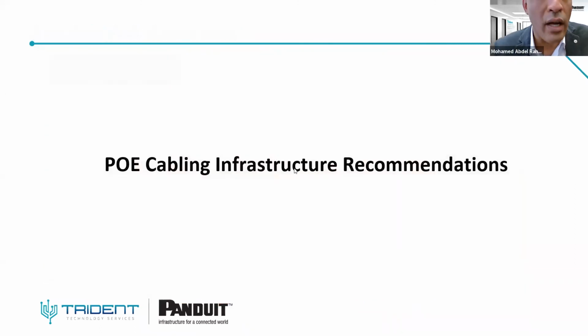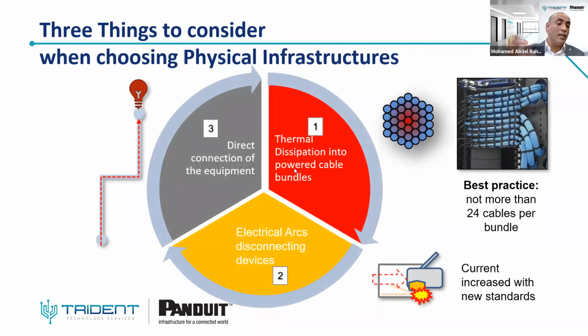So finally, you have only 2 minutes now, talking about the recommendations. What are the recommendations for the increasing high power? You need additional precautions when you are talking about cabling installations, to avoid overheating. You have 3 considerations when you are going to PoE. The first one is the cable wire gauge. As we said, starting from 23 AWG, it will be suitable when you are talking about PoE.